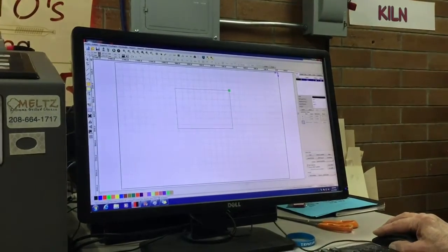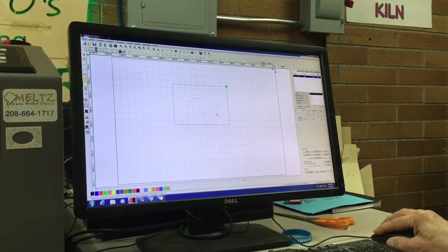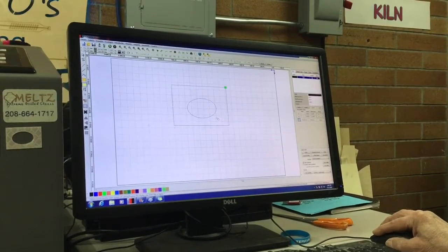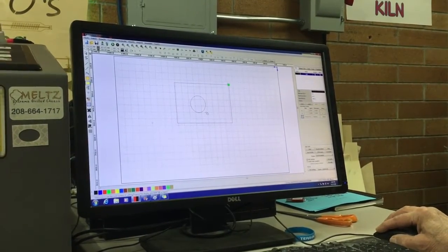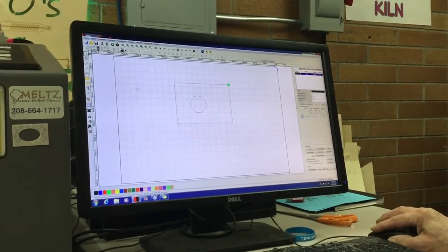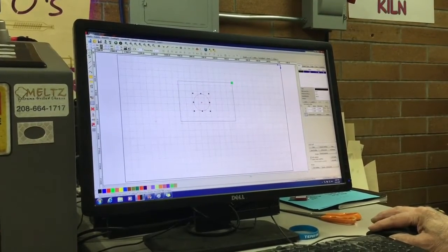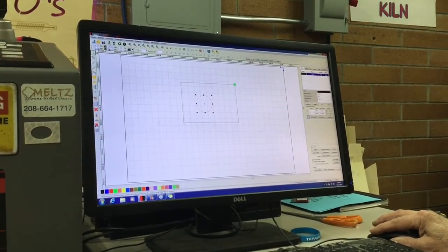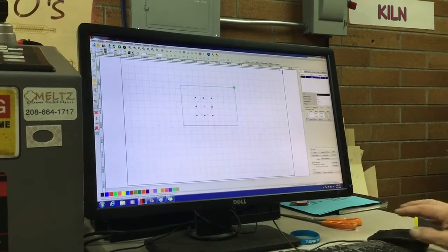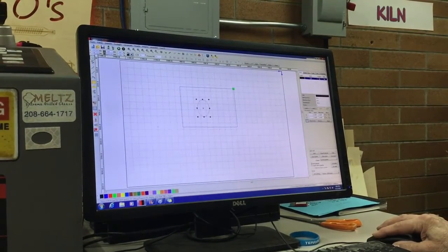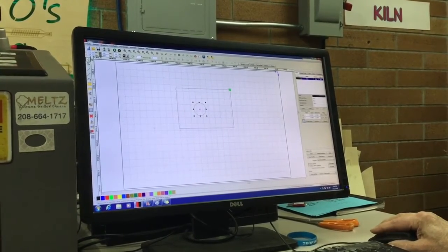So if you go to the circle tool, you can draw a shape that is any shape at all, elliptical or circular. If you want it to be circular, you could guess at how it looked, but you could also go directly to there, unlock this, and make sure that the height and the width were the same. So if, let's say we wanted a 100 millimeter circle there, we could type in 100 for that, and 100 for that, and now we have a circular part.